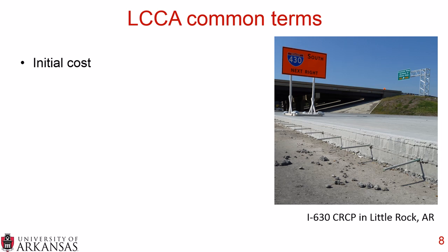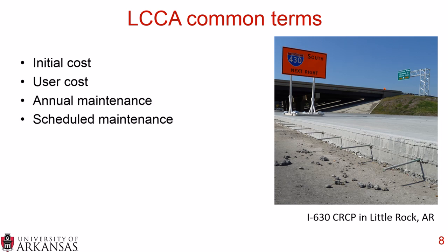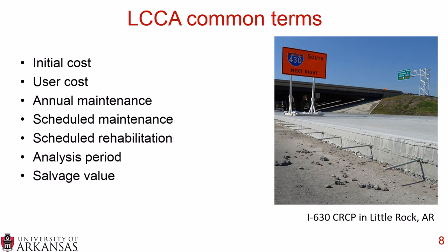So some common terms that you'll hear when we're talking specifically about a life cycle cost analysis are the initial cost, the user costs, what I call annual maintenance and scheduled maintenance, scheduled rehabilitation, we just talked about the analysis period, and then finally the salvage value. And this can also be represented graphically.